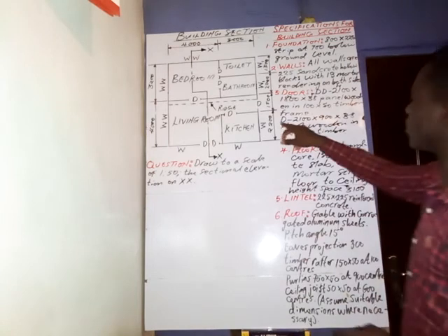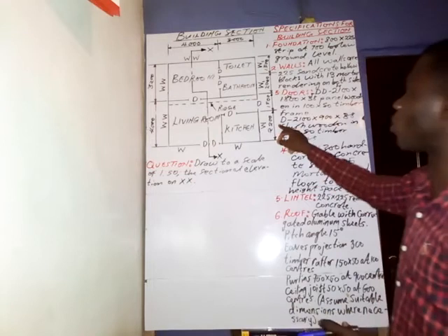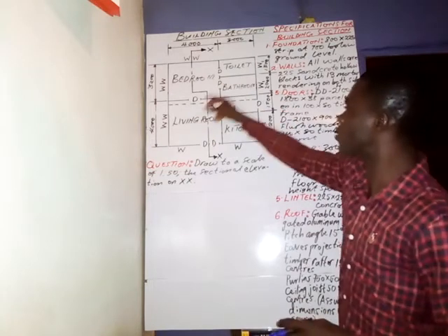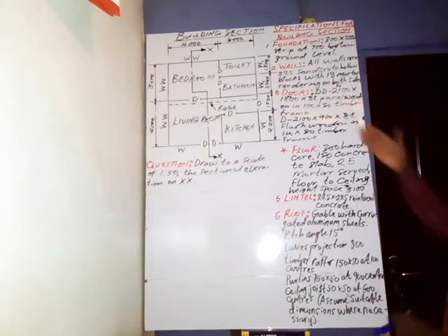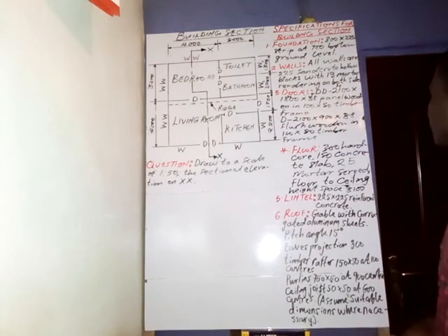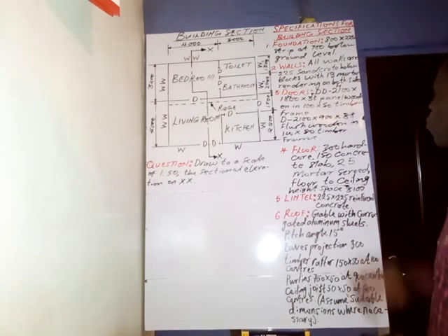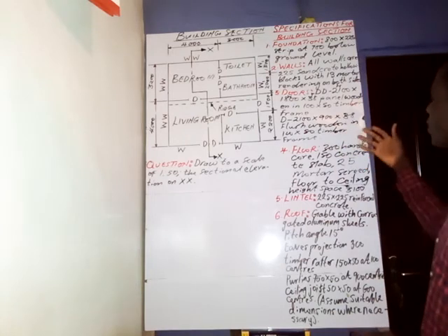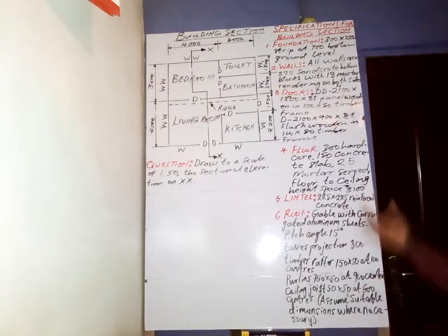That is for the double door. Then we have the single doors. These are single doors here. The dimension is 2,100 by 900 by 38, and it happens to be a flush wooden door in a 100 by 50 timber frame.